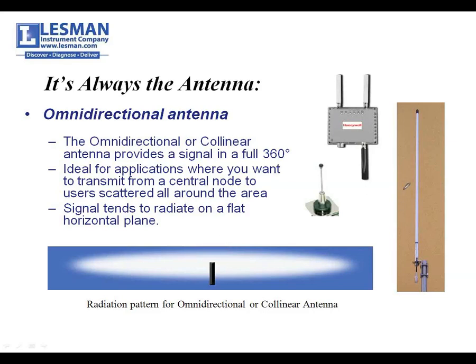This is an omnidirectional antenna, just like on, well, cars have fins now. They used to have antennas, but it's designed to send and receive information in a big circle in all directions. The standard little omnidirectional antenna, like on your car, actually throws a pumpkin-shaped energy bubble, if you will. It'll send and receive very high, not so wide. Works great when you need to get high from the bottom of the power plant to the top of the power plant. It works wonderfully. Doesn't give you a lot of good reaching distance.